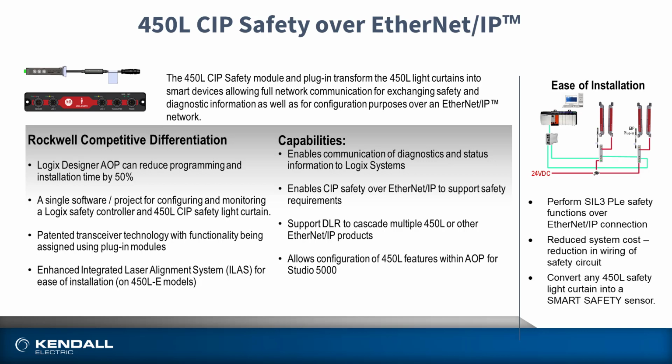The mentioned CIP safety module turns any 450L into a smart device. While installed on an active machine, the beam status can be checked to help find nuisance tripping. Smart device really means live coverage status and live diagnostics. We can now see individual beam strength of each device from the controller.